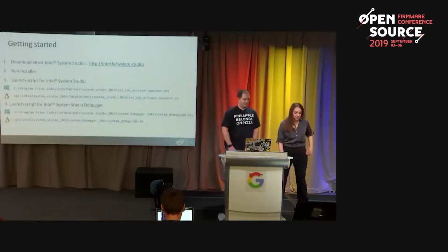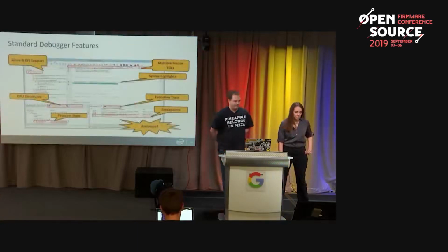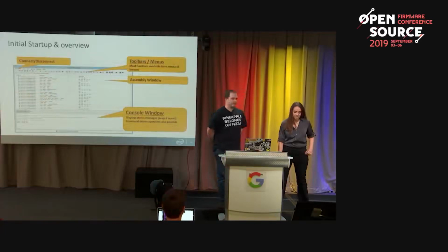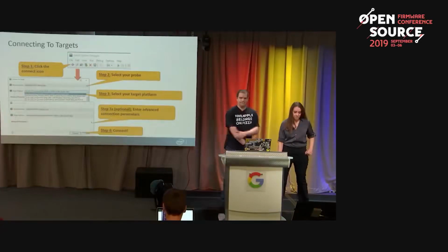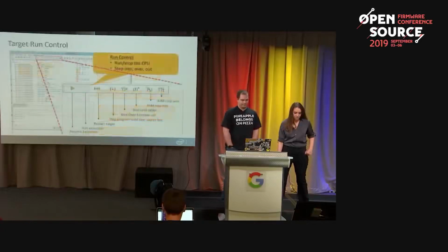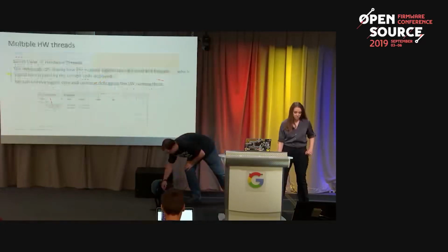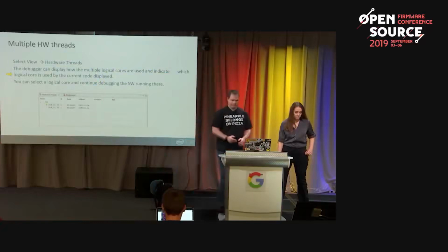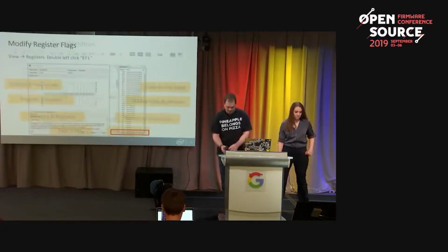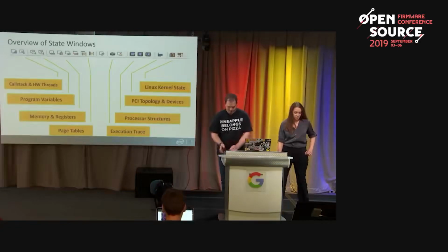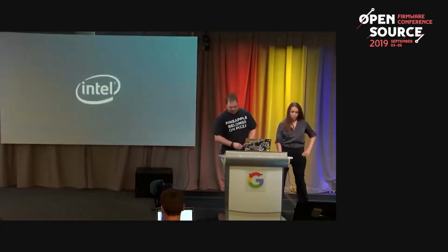It tells you where to get stuff, where stuff is, all the different things that are available, like what's what and where's where. Where the trace is, where the breakpoints would be. It's good for reference. Connect, disconnect. This is your console window. You click to connect, you select the probe, which is usually DCI, what platform you have, and so on. You can resume, halt, restart, step over, step into. You can look at your threads. You can see all the register flags. You can see variables, page tables. That's it. All the things.